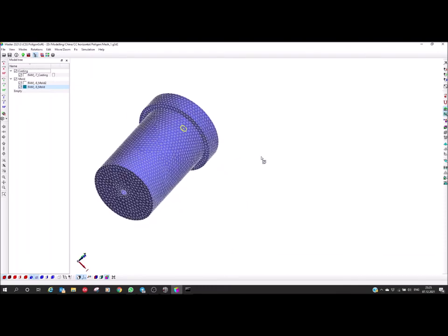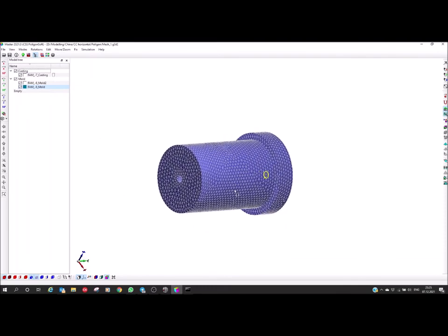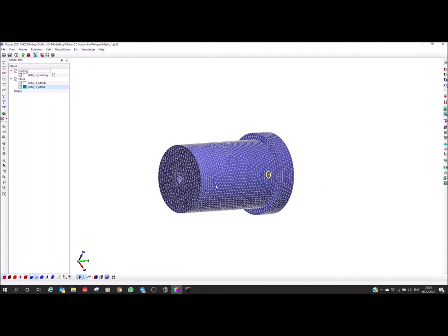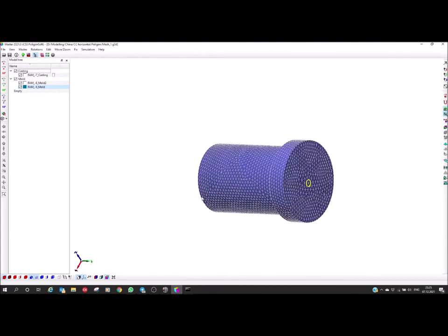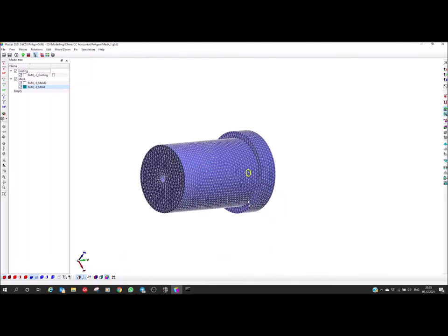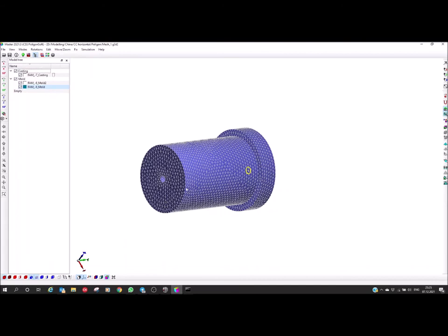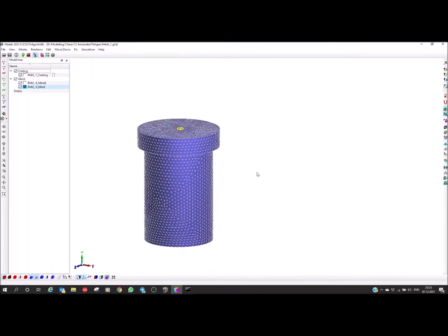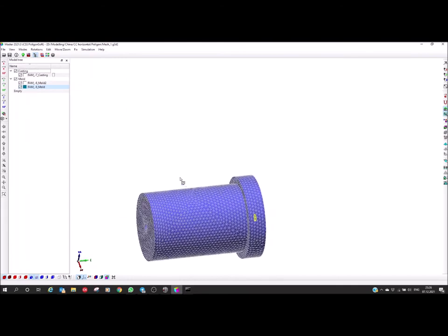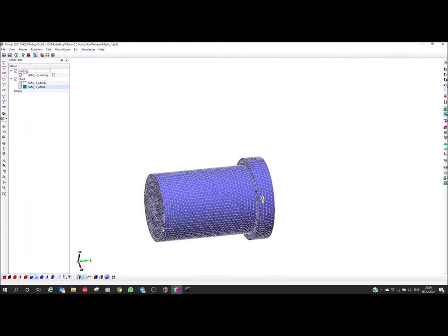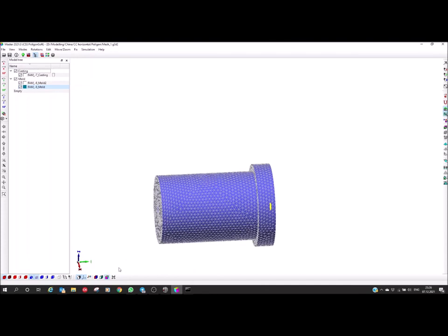But in horizontal centrifugal casting the centrifugal force is much higher than gravity, so we can simulate this type of centrifugal casting, but we need to orient our geometry like here and set up the rotation axis like this along the y-axis, and we will simulate only solidification. It doesn't matter that our gravity vector has the wrong direction.